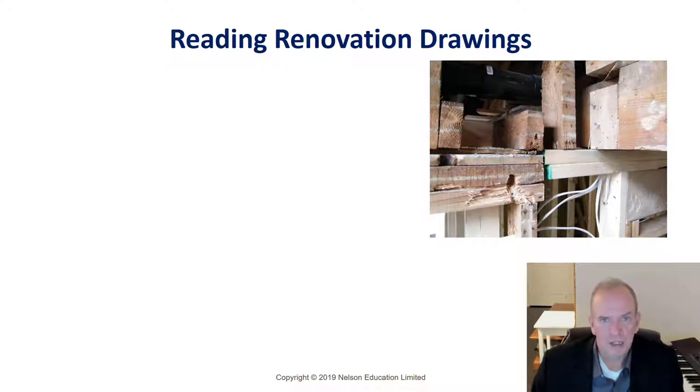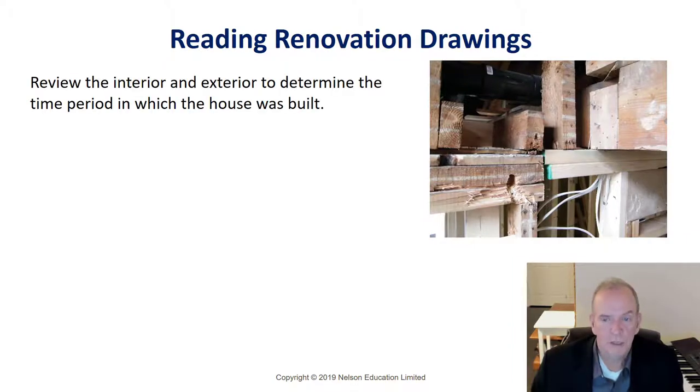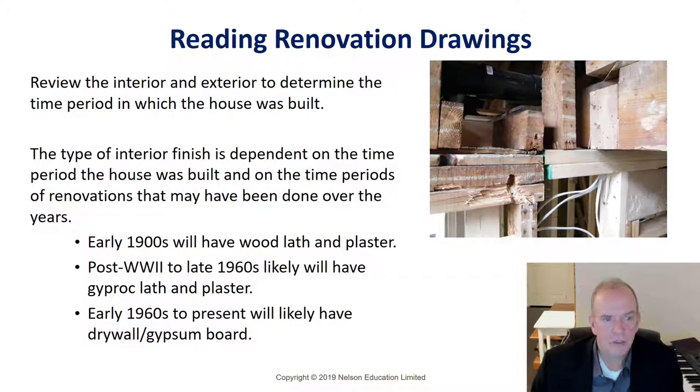It comes in sheets, very quick to apply, doesn't require the same kind of skill that plastering did. Doesn't take the same kind of time either. So big differences in the technology over the years, and then you have to tie old to new. These are some of the challenges that you run into. And early 1900s, anything that's pretty much before World War II was lath and plaster.